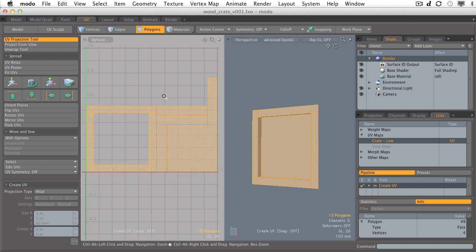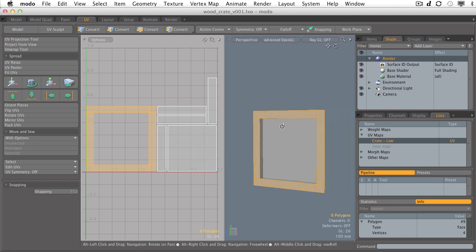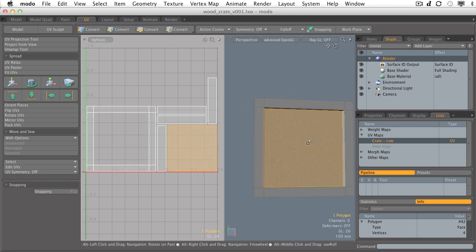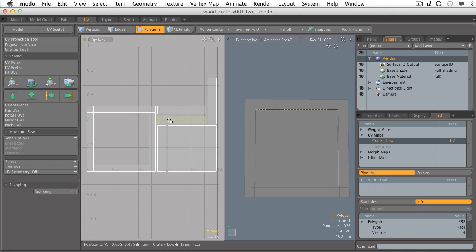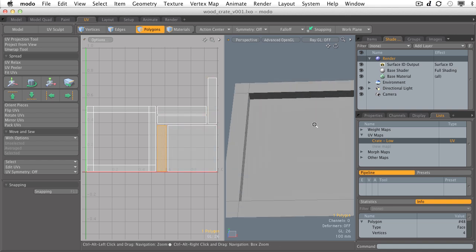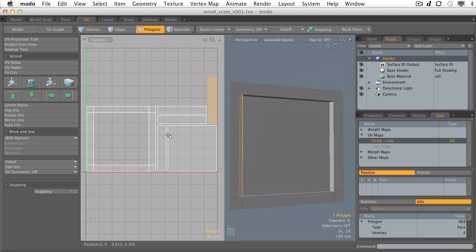Now, the Atlas projection did a pretty darn good job, and it did some really good things. For example, the face of this entire cube, or this entire surface, is looking pretty good. The proportions are good, the size is about good. This inside cube, also looking pretty good. The orientation's right, the proportion is generally right, but where it went wrong, and what it didn't do a really great job of doing in unwrapping are these guys, okay? It's completely ripped all of these polygons apart from each other, and I need to go back and combine them and attach them to either this guy or the faceplane.